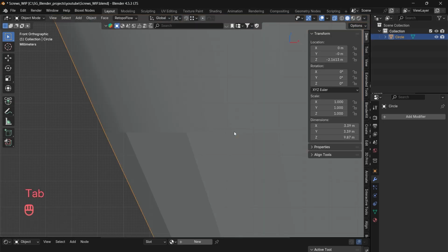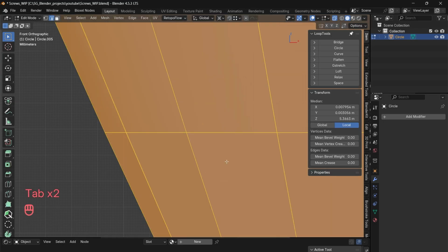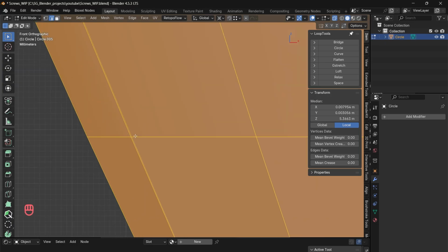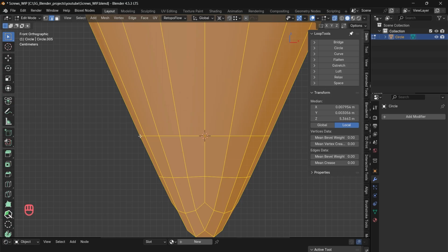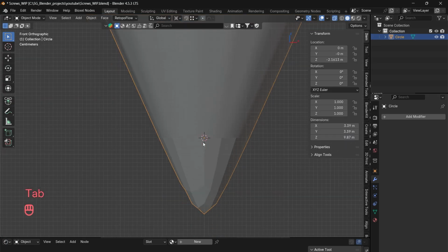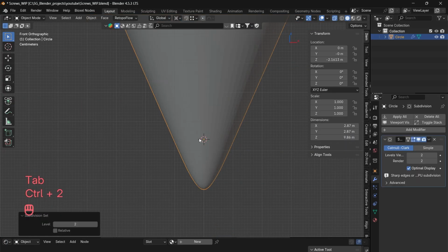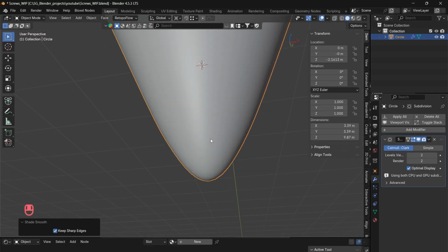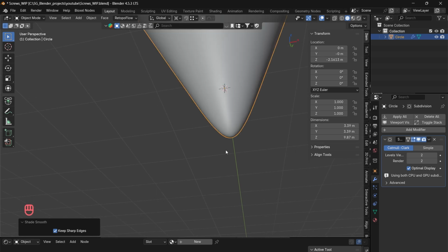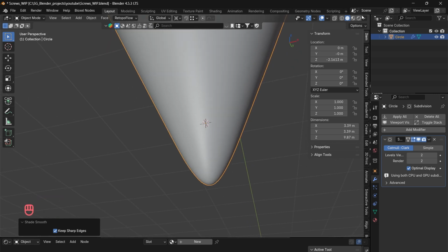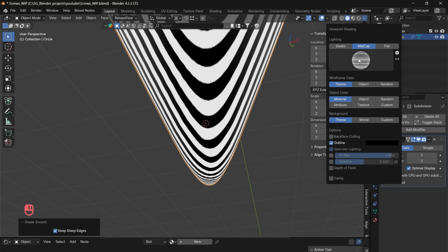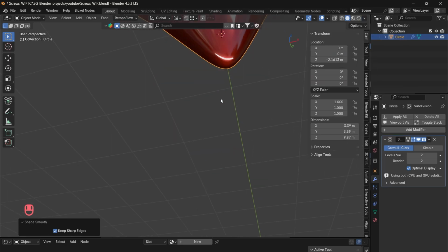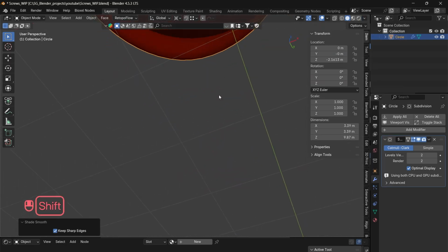And if you remember the initial part of creating the tip, we started with the same 16 vertex. That means all the duplicate vertices which got created here got removed. And so now if I apply Control 2 subdivision again, apply shade smooth and disable the X-ray vision, you will see that our job is done. Look at this beautiful tip now. Okay, no shading effects here. To verify that, let me go to the matcap, choose a matcap of this. You'll see, look at this.